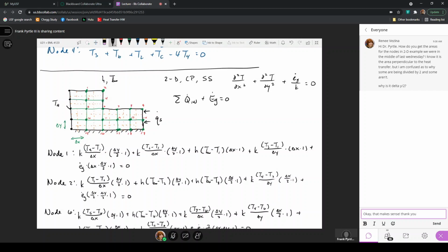So the areas for each of these nodes are directly defined according to the grid spacing, that is delta x in the x direction and delta y in the y direction, and we use the resultant geometry to define volumes for the generation and lengths for the heat transfer that's occurring by conduction or convection on a boundary, where that area is the area for heat transfer between the surrounding node and the node of interest, or the surroundings if it's on a boundary.